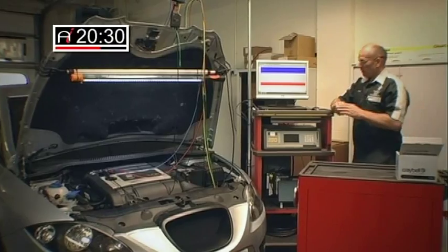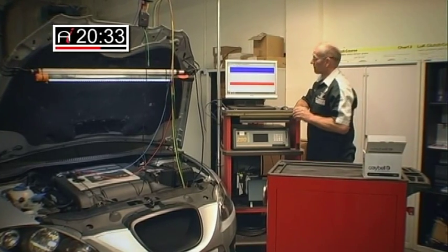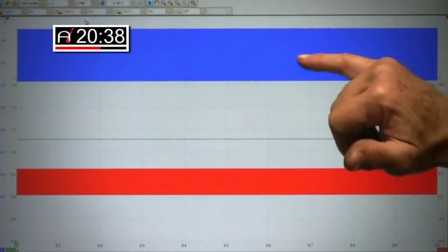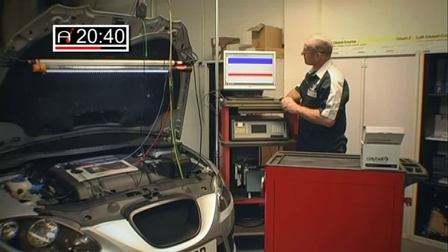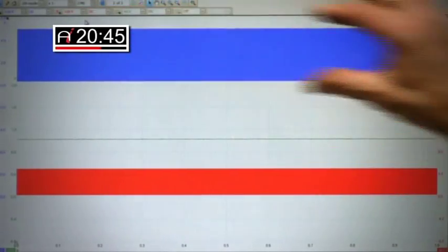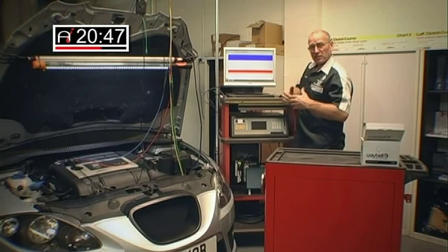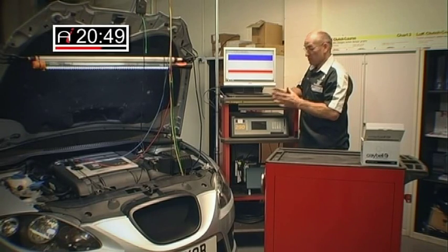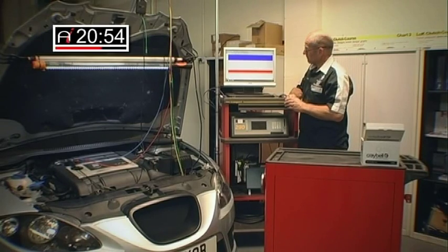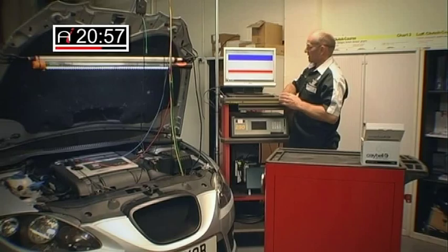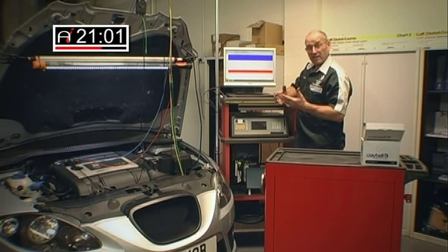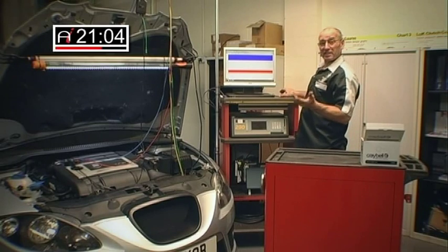The actual setup now of the oscilloscope. The actual frequency signal on channel 1, blue, is over a 5 volt range. The reason it's shown as an envelope is that it's a high frequency, somewhere around 2000 Hertz at present, the engine's idling, and because of the time base we've selected, the signal becomes compressed. So if you want to look at that in detail, of course we need to divide into the voltage, into